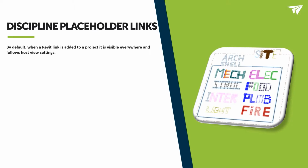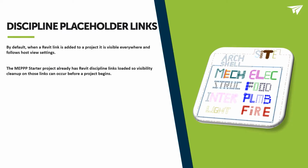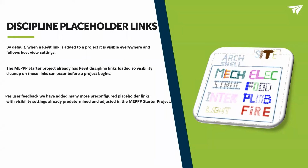So what they've done here with the discipline placeholder links is they've already added a ton of visibility settings into those links so that common things that you're going to get from other trades like annotation, and I'm sure other things that I can't think of off the top of my head, potentially color coordination, those kind of things are all going to be preset and ready to go. So all you have to do is reload from, select the link from whoever you got it from, and all of those properties will be applied to that new link.